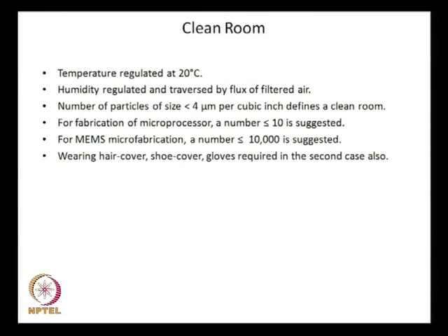One thing I would like to point out here is that typically with the replication method, when it comes to making a plastic MEMS device, when you make the mold, a clean room is a must, because you have to make a silicon master. You have to make a master which you either press as a stamp or use as a mold on which the liquid molten plastic would be poured. When you make that master, it is important that you have the clean room, but when it comes to the replication method, the requirements are not that stringent.